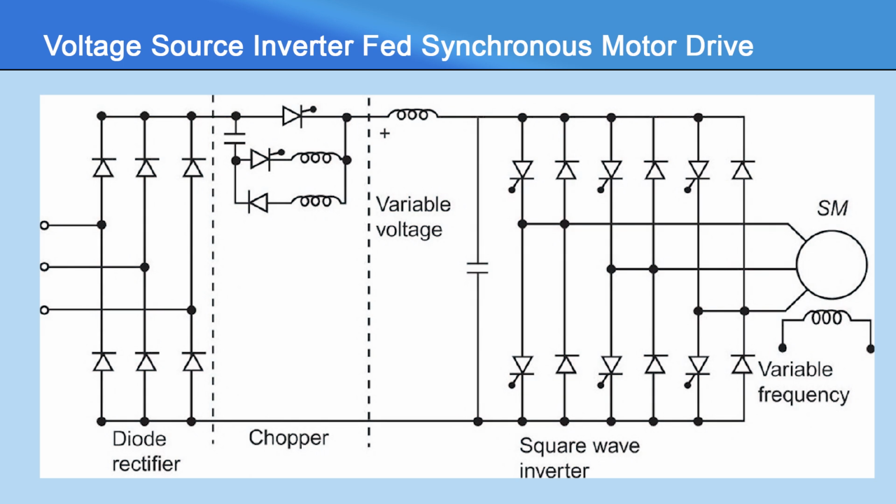The third alternative is to interpose a DC chopper between the rectifier and the inverter, as shown in the figure. Thus, the system may appear as if 3 simple converters are used to give the desired result. It is possible to reduce the size of the DC link inductor by using a synchronous control of the chopper.